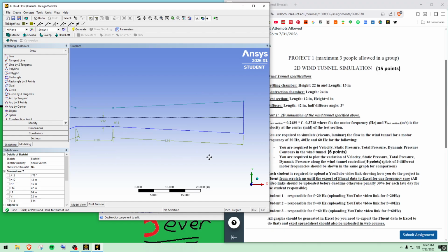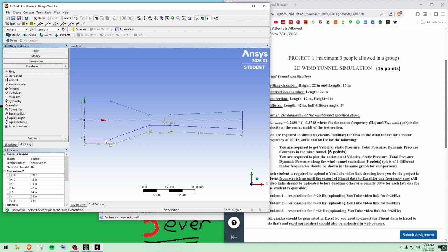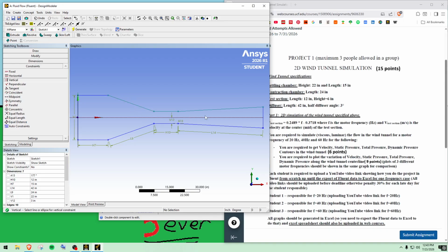Right, yeah. And we just make sure our lines are all straight with constraints. Horizontal. Click on that. Click on this. This. And then our vertical. And as you can see, these ones are kind of like a greenish blue. So I am just gonna hit these with the dimension. So L15 is 24 inches.